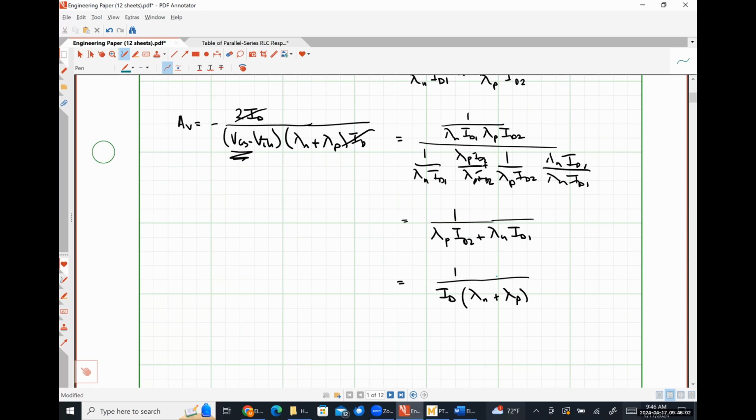We don't have to worry about base currents or anything like that because they're not BJTs. If we know the current flowing down through transistors M1 and M2, and we know our supply voltage, we know how much power is consumed by the right-hand half of the circuit, which tells us how much power is left over for the left-hand half of the circuit.